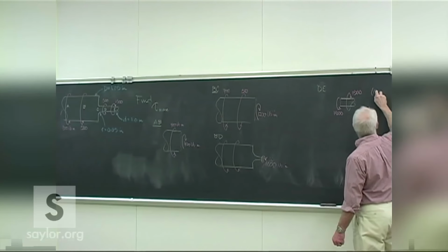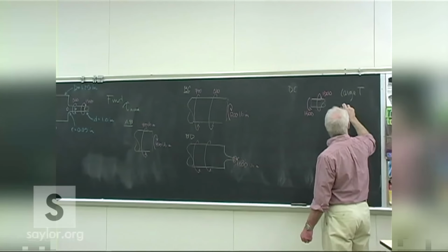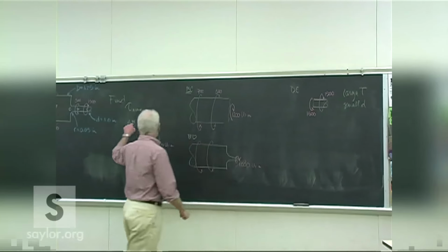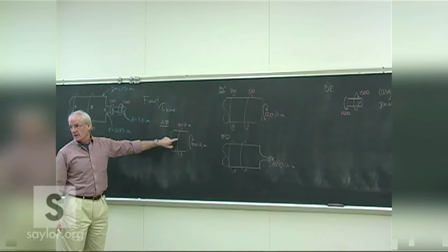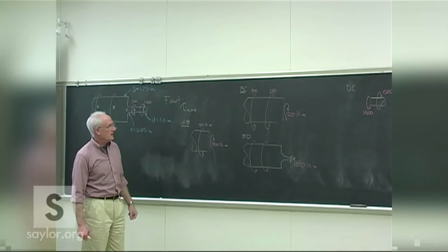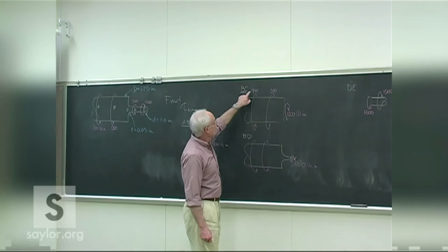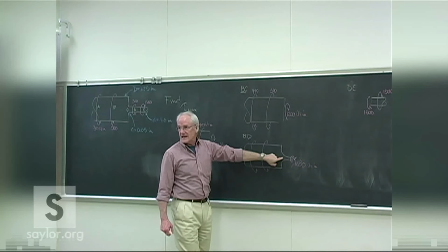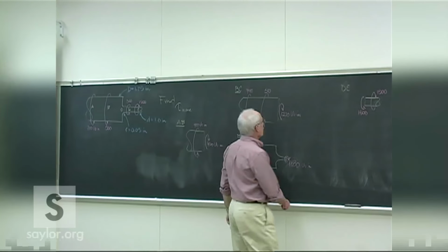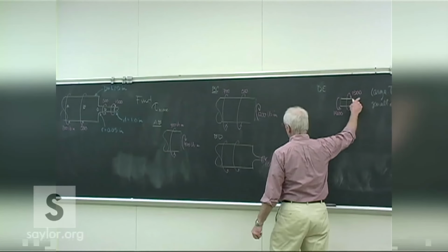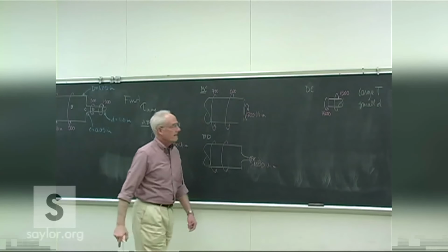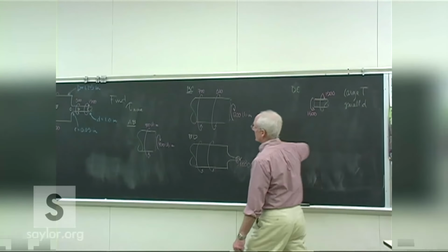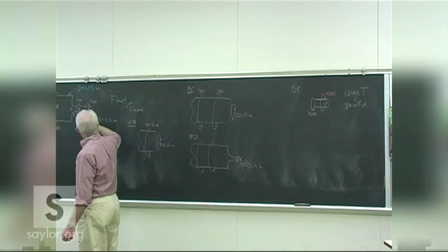This is a large load and a small diameter. So A to B is much better off, much lower load, but a much greater diameter, so we're not even concerned with A to B. B to C is no real trouble, but we are worried about what happens at the transition. And then we're worried what happens in this region there, when we're down in the smaller end of the shaft, out here between D and E.